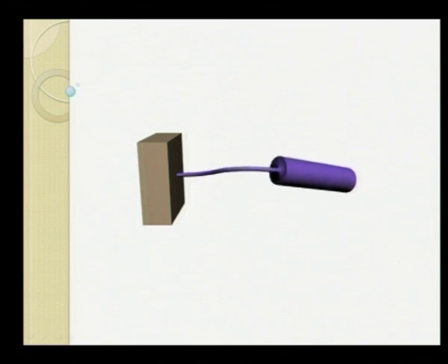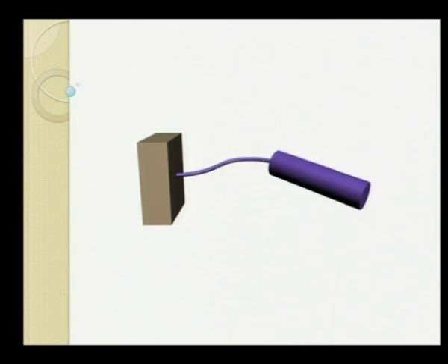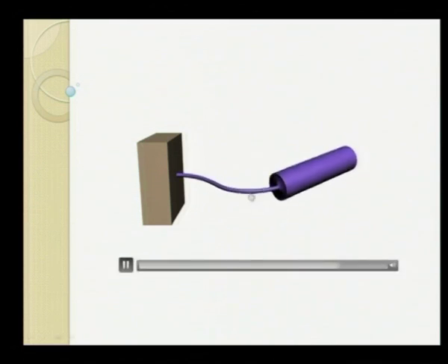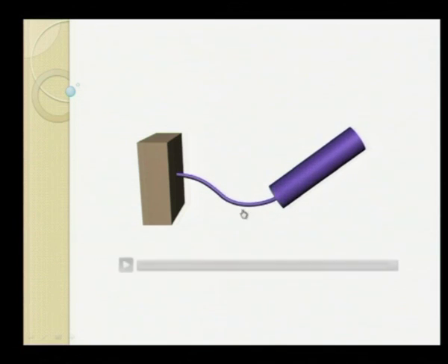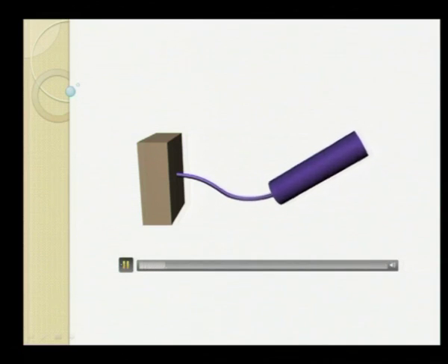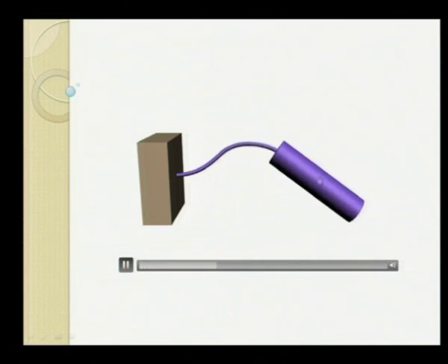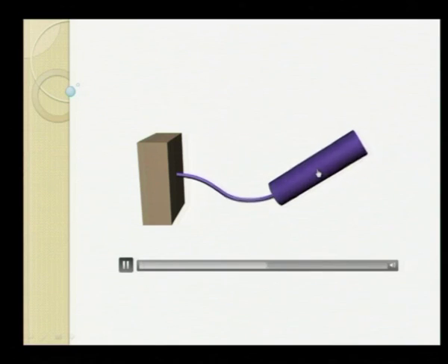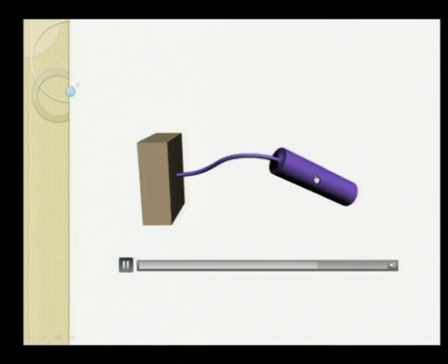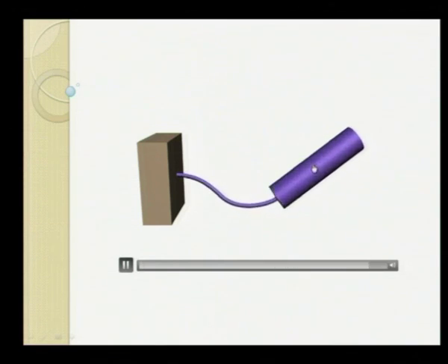In fact, when we are having synchronous whirl, the shaft bends in a particular configuration and remains in that position, and the whirl takes place. So you can see this is a pure rotation of the shaft, because we assumed there is tilting about its center of gravity.